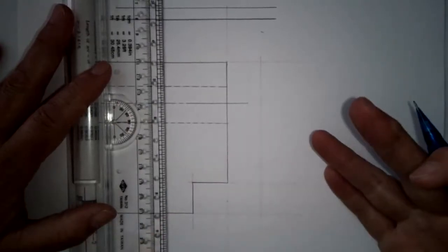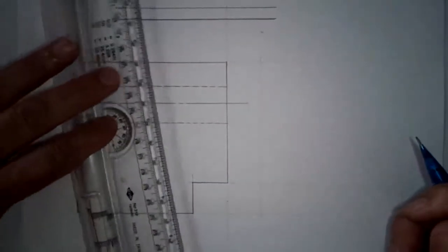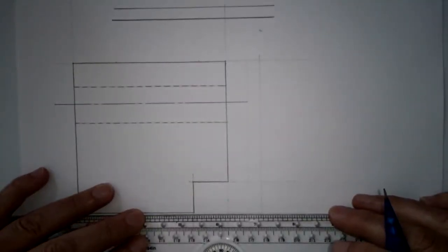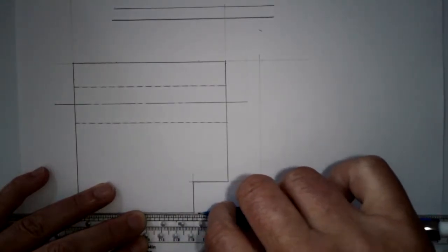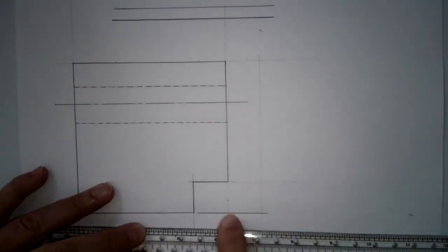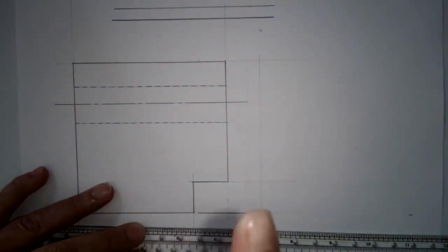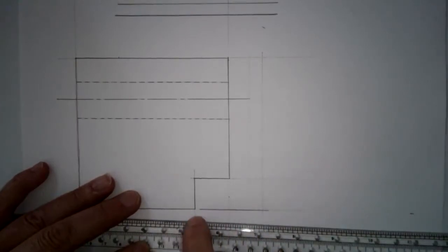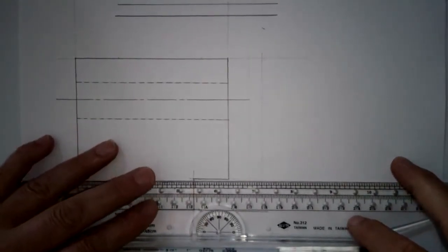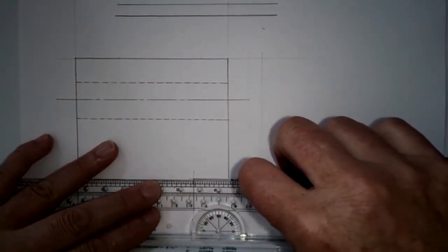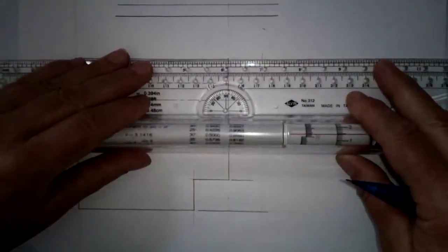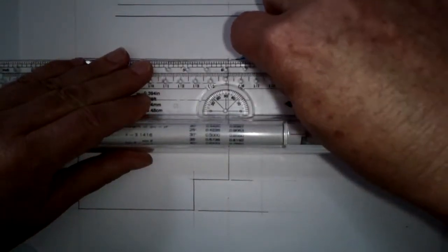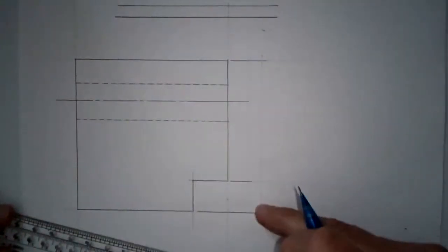So now I'm ready to put in my actual thin lines for all of these things. I'm going to start off with my extension lines, and you want to mind the gap, meaning make sure there's a gap between your extension lines and the actual object lines, because that's one of the cues that tell us that the edge of the drawing is stopping and the dimension lines are beginning. Here we want to be careful to not extend that extension line too far. It's only going to go to the first dimension line we have here, and then we're going to go up to this one and do the same thing, minding the gap, have that extend to the second dimension line.